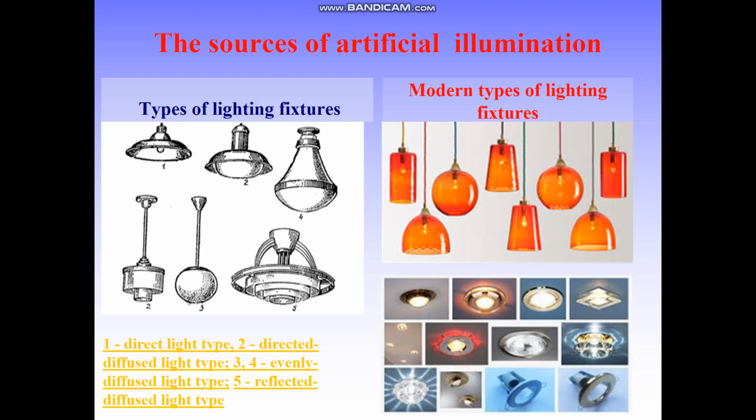Today, electrical lighting is mainly used because it provides sufficient and uniform lighting of premises without heat and byproducts of burning. The filament lamp is filled with inert gas, and the light energy is generated due to heat of the tungsten filament during the electric current passing through. In recent years, fluorescent lighting has become widespread, using a matte glass tube with mercury fumes inside.